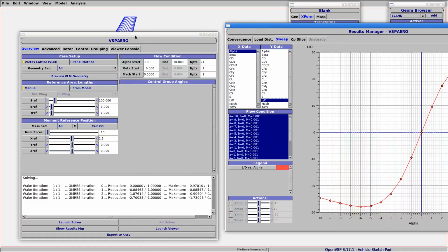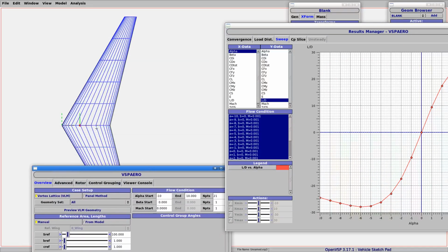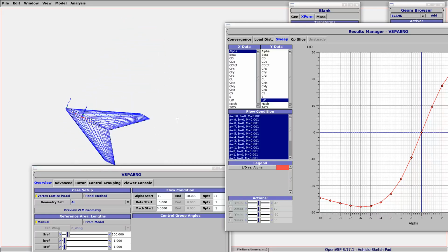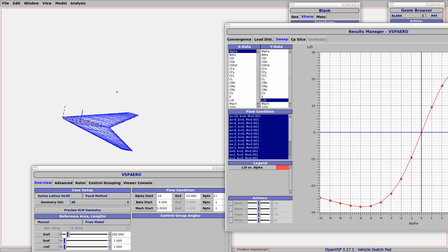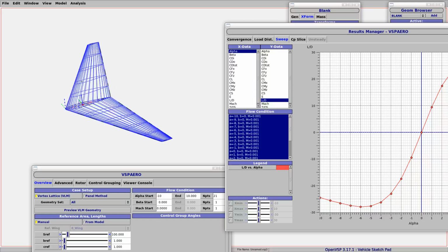So what we need to do really is make it so that this wing is going to angle itself upwards relative to the air. And a couple of ways we can do that. One is to use an airfoil that has a reflex in it, so that as the air leaves the trailing edge, it's going to be flicked upwards a little bit, so that the trailing edge will tend to press downwards a bit, so that as it flies along, it will be at more of an angle like that. I showed you before how to change the airfoil section, so you could try that.